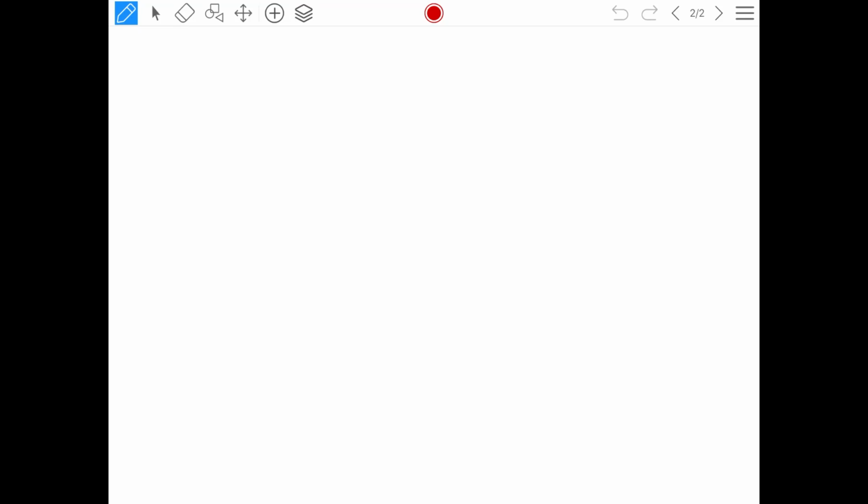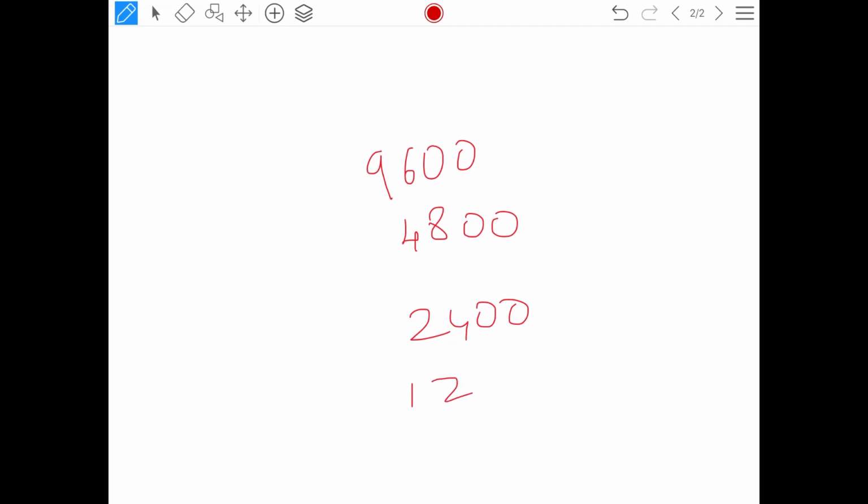Some of the standard bauds followed are 9600, 4800 baud, 2400, 1200, etc. There are different bauds that are followed in the microcontroller. We can implement this baud using the timer counter register. Especially, the majority of the time we will be employing the timer 1 register for implementation.